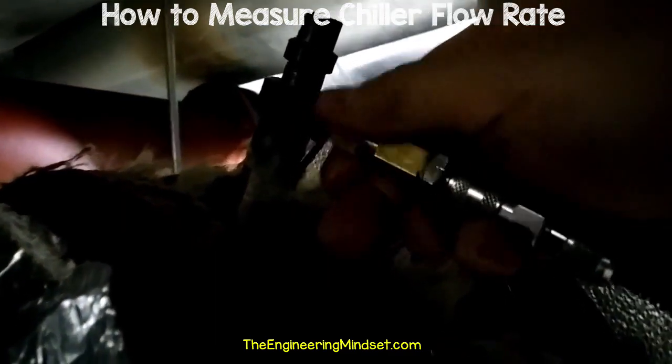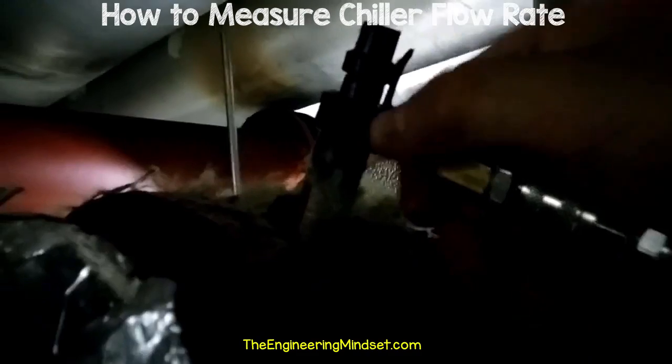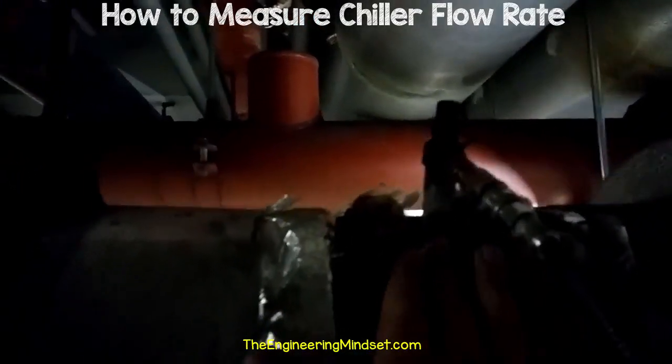You might need to change the connection fitting depending on which valve has been used. You'll also need to check that the threads are all clean, as these are often covered with dust and dirt. Just turn it hand tight and ensure that it isn't leaking. Lastly, just double check that you've connected the correct hose to the correct side.